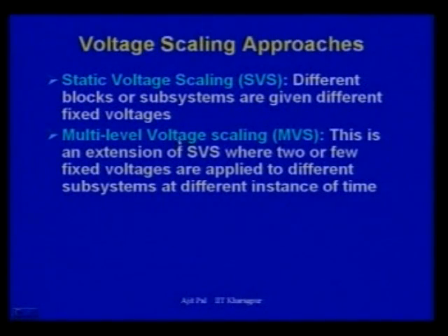And multi-voltage scaling is an extension of static voltage scaling, where two or a few fixed voltages are applied to different subsystems at different instances of time. That means here it is kind of dynamic. Besides doing the design at design time, at run time you can also apply different voltages to different subsystems to reduce power dissipation.